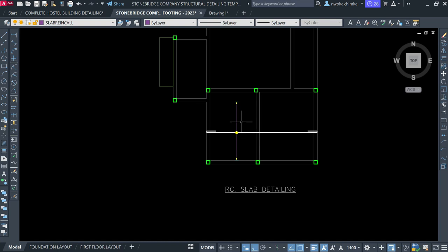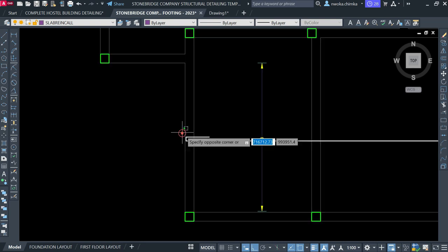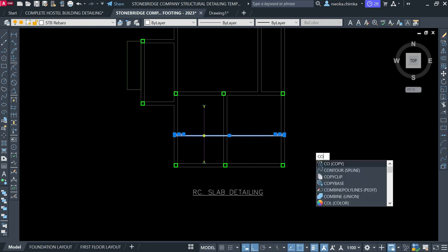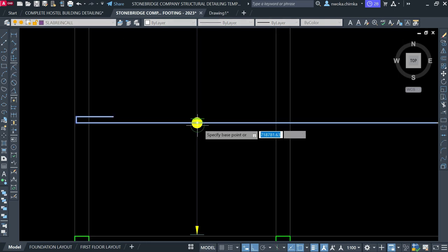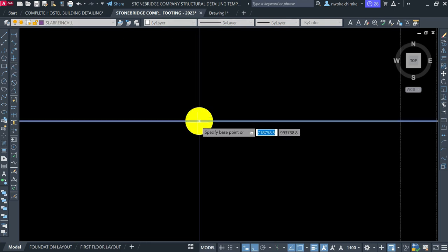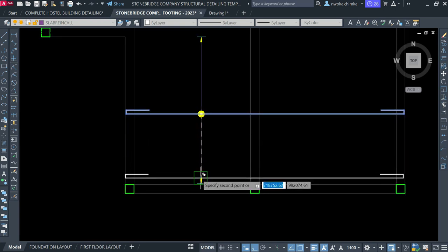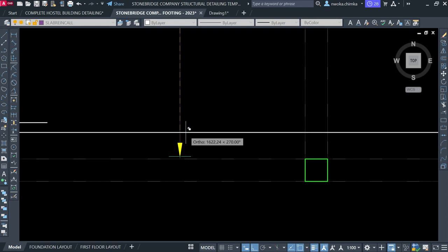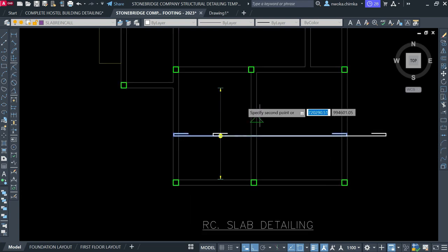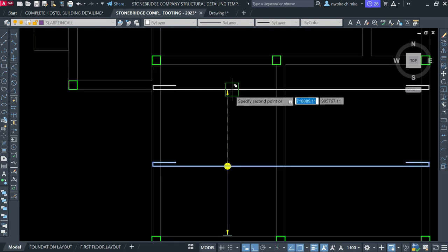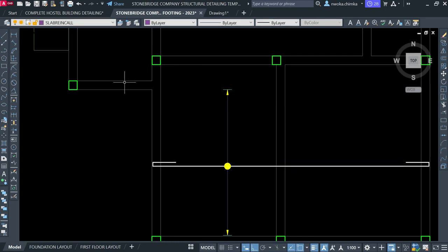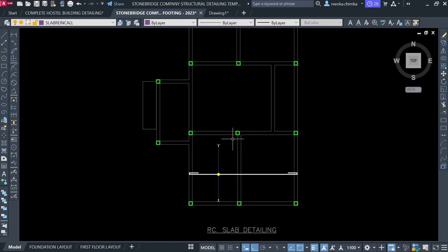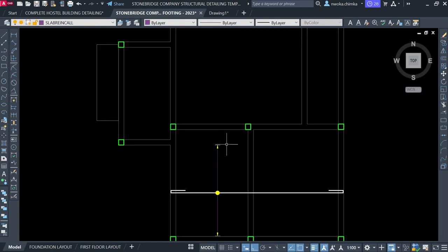Okay, so right now you have now seen how this bar, this bar reinforcement is running all the way down from this very point, and our spacing is 200, so it's running all the way down from this very place here right now, and running with 200 all the way down to this very place. So when it gets here, it will stop because there is a change of shape, as you can see it here right now. So it will stop there, and then another bar again will not continue from this very point.